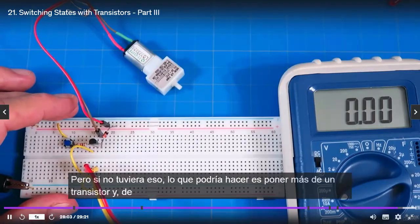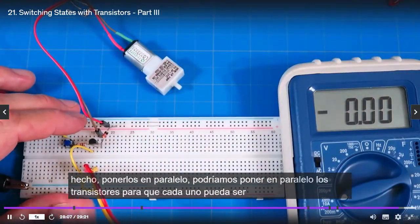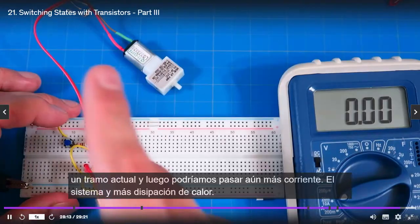But if you didn't have that, what you could do is put more than one transistor in parallel. We could parallel the transistors together so that each could be a current leg, and then we could get even more current going through the system and more heat dissipating.